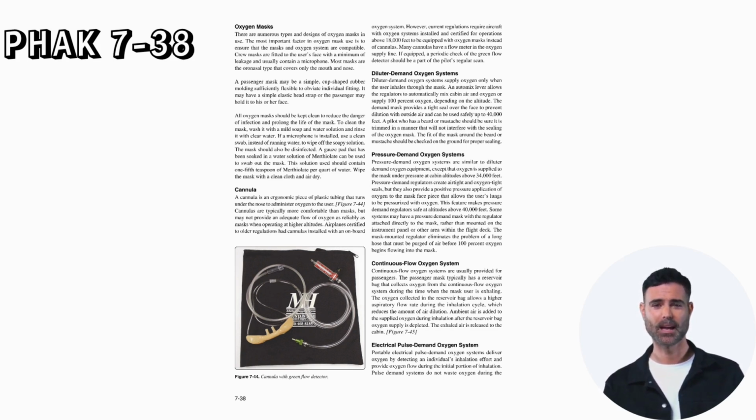Some systems may have a pressure demand mask with the regulator attached directly to the mask rather than mounted on the instrument panel or other area within the flight deck. The mask-mounted regulator eliminates the problem of a long hose that must be purged of air before 100% oxygen begins flowing into the mask. Continuous flow oxygen system.